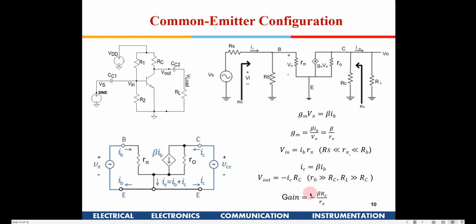Okay, so this negative sign symbolizes that the signals will be out of phase. Like if you increase the voltage here, more current will flow here. Okay, so the output voltage here will be VDD minus that much, right? So the signal will start dropping. The voltage here will start dropping out here. Similarly, when this signal is going negative, lesser current will flow here, and hence there will be lesser IR drop, and the signal level will go high. So you will find whatever signal we are observing here after the capacitor, it will be 180 degrees out of phase than what you have applied here. So that is why this negative signifies out here, right?